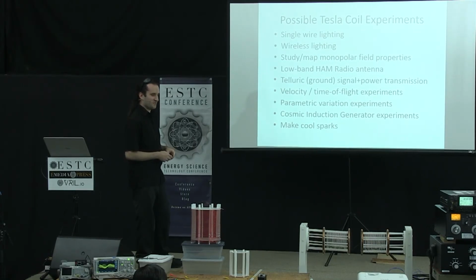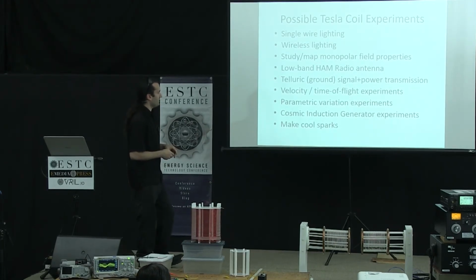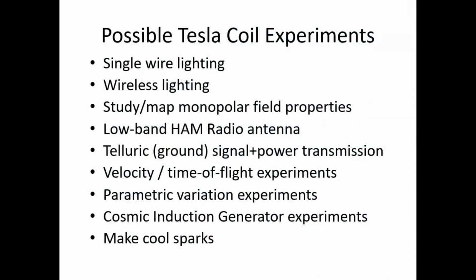So instead of being 100 feet in the air, you're going to have to drive a ground rod or something, drive 20, 50 ground rods and get a ground impedance less than 1 or something in the water table. Maybe you toss a wire into the ocean or something like that to get the lowest possible resistance and drive one of these. But if you do it right, you should be able to get long-range propagation through the ground.